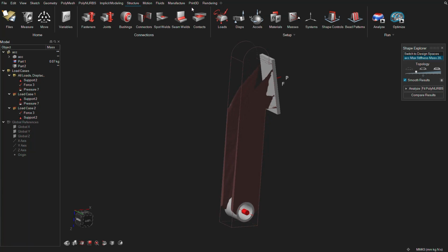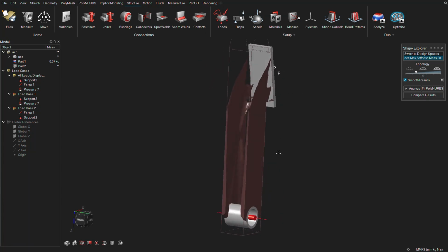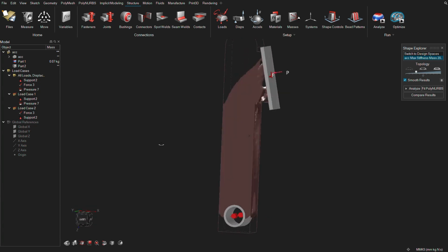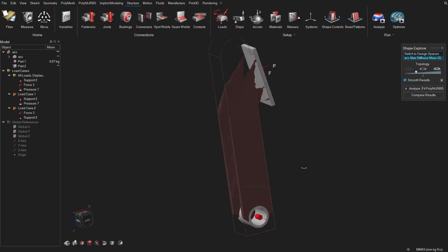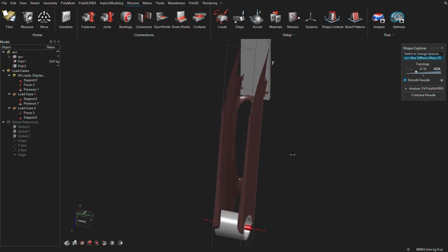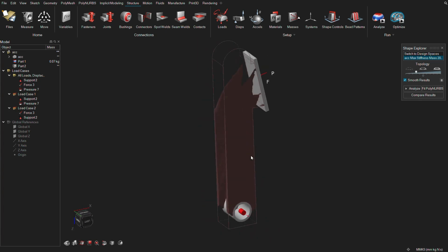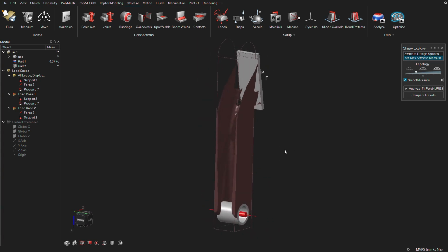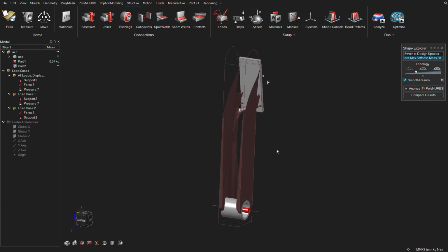So this is our outcome, our pre-final design. As we can clearly see, there are 2 parallel plates joining the lower cylinder. The bottom cylinder is connected to the top rest plate by the 2 parallel plates. By this observation, I'm gonna aim at manufacturing the pedal through sheet metal manufacturing, and by bending of sheet metal we are gonna manufacture this.